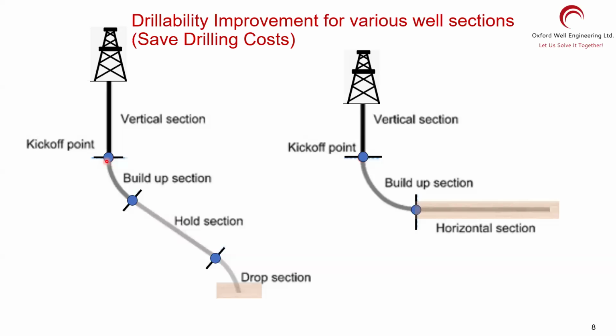Kickoff point. Where do I need to put my kickoff point? What governs it? There's a lot of engineering modeling people do, and people choose the kickoff point which makes it easy, a foolproof way. Foolproof means sometimes you fail to kick off. Then what are you going to do? You have to make the dog legs bigger. That's a very bad idea, because if you make the dog leg bigger, there could be a problem running the casing. All kinds of bad things happen if you do not get the kickoff point right.